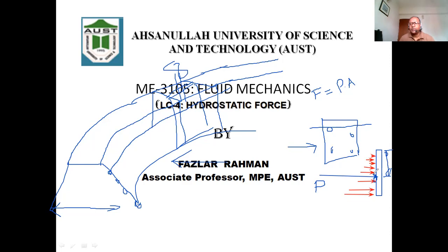then you can design the gate properly, because you have to make sure what the thickness of this plate will be, what type of material you use, other things on both sides, and also you have to make the support strong enough that it will carry the load, because the pressure force ultimately works right over here on the plate, right?